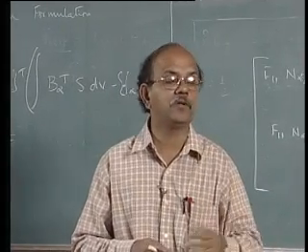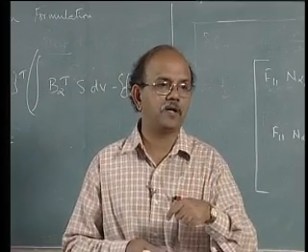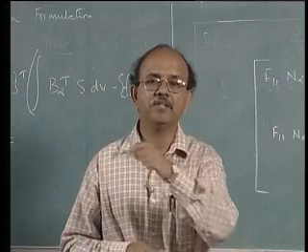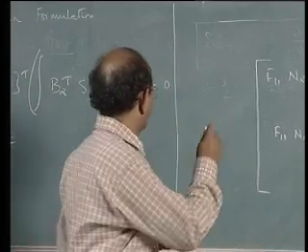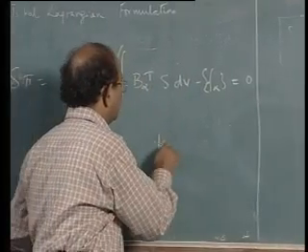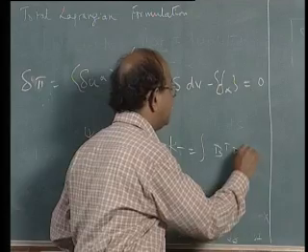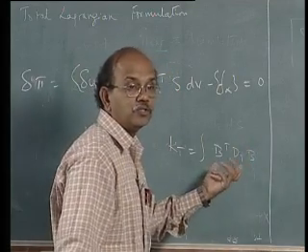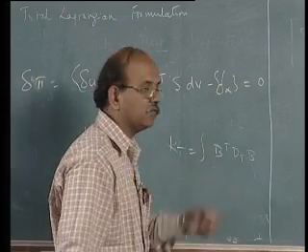So I was able to write this as, how did we write? B transpose ∂σ/∂ε into ∂ε/∂U into δU. So that we had KT, if you remember, we had a lovely KT term without much problems, which was B transpose DT B. This is for the small strain nonlinear problem. This is the KT we had.